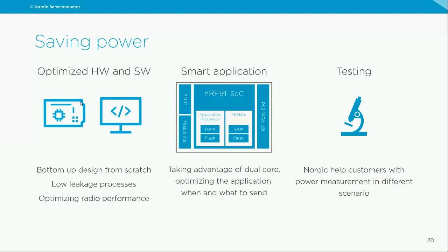and to optimize everything in the modem for those two protocols. That doesn't only mean we can optimize for those protocols, we could also optimize power management and sleep modes so that we can very efficiently turn part of the modem to sleep very often, even during RRC idle mode or RRC connected mode, because even though the transceiver is transmitting data, some parts of the modem can still shut off, such as DSP or other features, in order to save power.